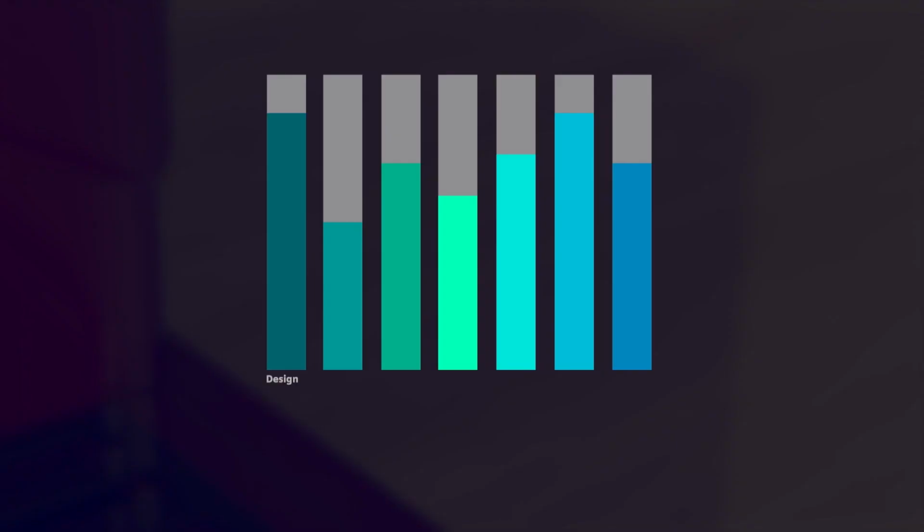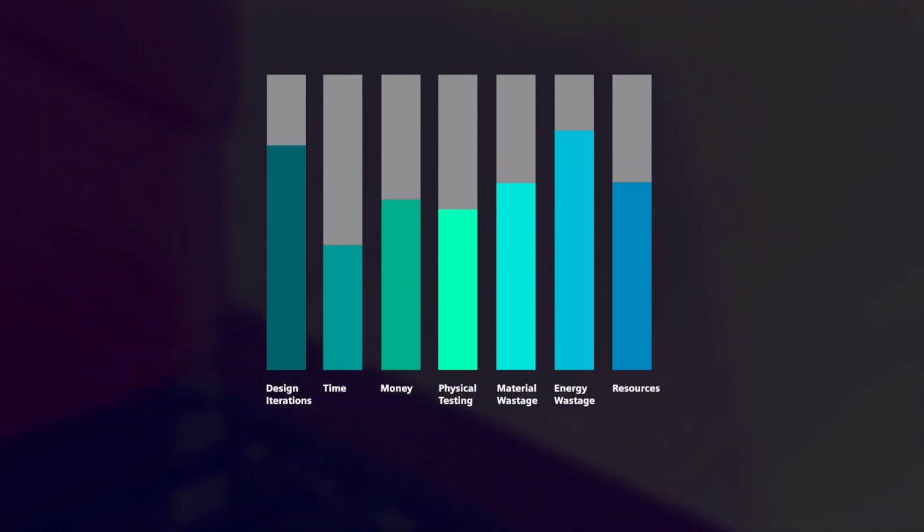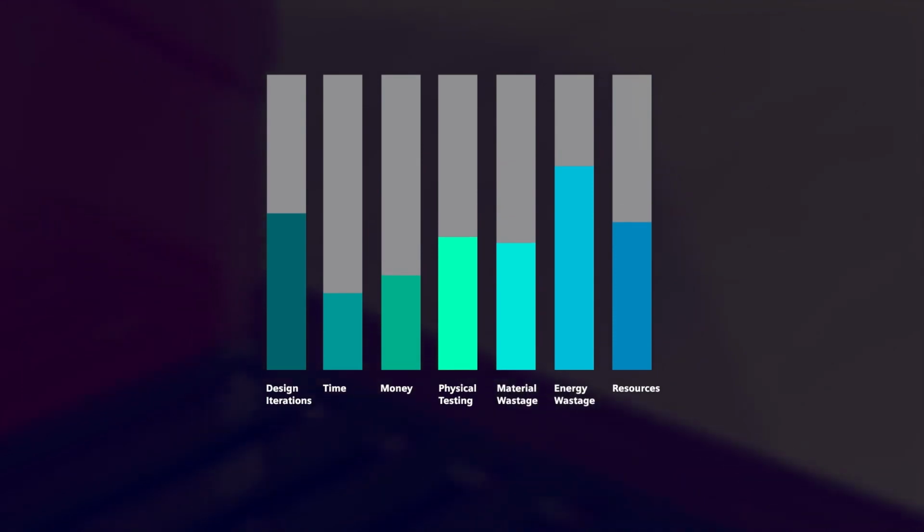Now we've added in all the necessary moulded plastic features, including bosses, snap fits, ribs, grooves, and drafts. Next, we can run an additional overall validation of the part and its features. We can see some warnings about certain features that we may need to investigate further to avoid defects, but overall, the part looks ready for manufacturing. Validating design for manufacturability early in the product development process means fewer design iterations before going to market, saving the company significant time and money.